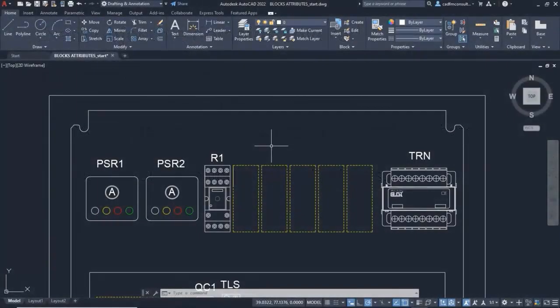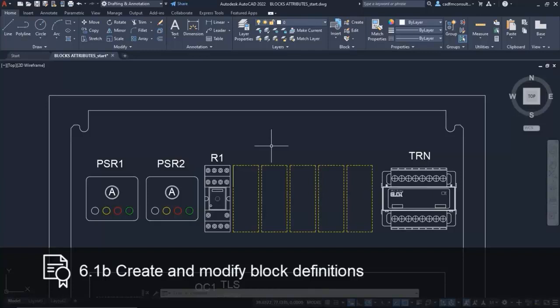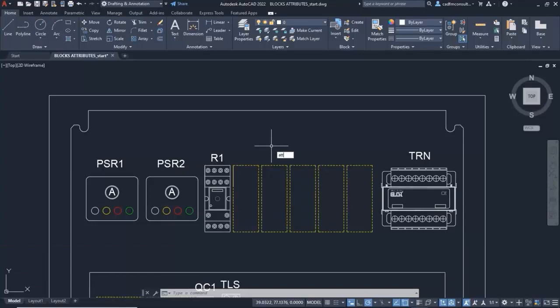When we created our block, we made sure that 2 of the attributes in the block were invisible. Now what I can do is utilize a really useful command in AutoCAD to display those invisible attributes if I want to. So I can use the attribute display command, or ATTDISP. Now I'm just going to type this in, ATTDISP. And you can see with the dynamic input it just pops up automatically, and on the suggestion menu there's only one command called ATTDISP in AutoCAD. When I press enter now, I can enter my attribute visibility setting.